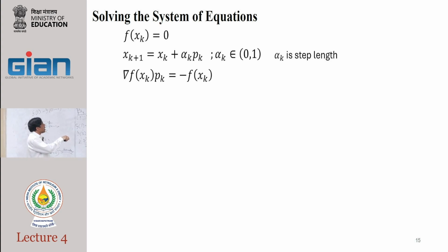This is the approach behind all the implementations that you will see. These are all derivative based approaches. Internally, Aspen does not use any derivative free approaches. There are some newer generation approaches showing up, but all approaches that you will see as part of ACM and ADSIM are derivative based. They are all variants of Newton's method, different flavors of Newton's methods.